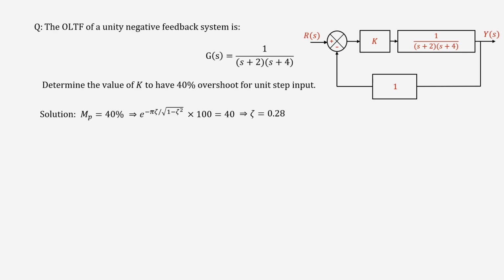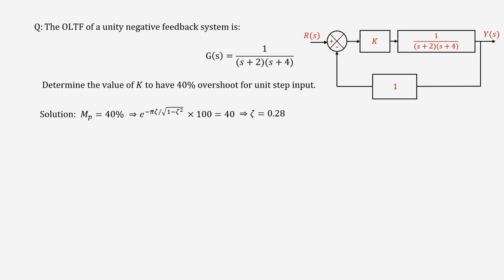Remember in case of Bode plot when we had discussed, that was log 10, the base was 10. In this case this is ln that we are talking about. So, always remember all these things, these are subtle things, but these are the things where you make mistakes and then you will keep on scratching your head as to how to solve the problem. So, always remember these subtleties. Now, here we have zeta equal to 0.28.